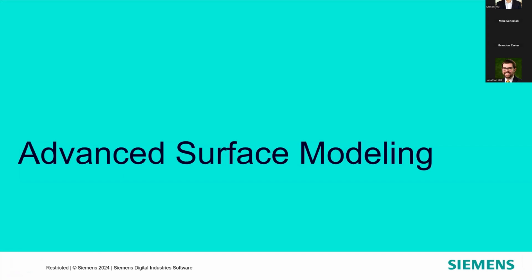But the next step is into some of our advanced surface modeling. So NX, with the different levels of service that you might purchase, the initial ones allow you to sketch, use the spline, loft surfaces, some basic through curves, some simple sweeps and things like that. But as you move on to more detailed surfacing, the advanced surfacing tools are really helpful.